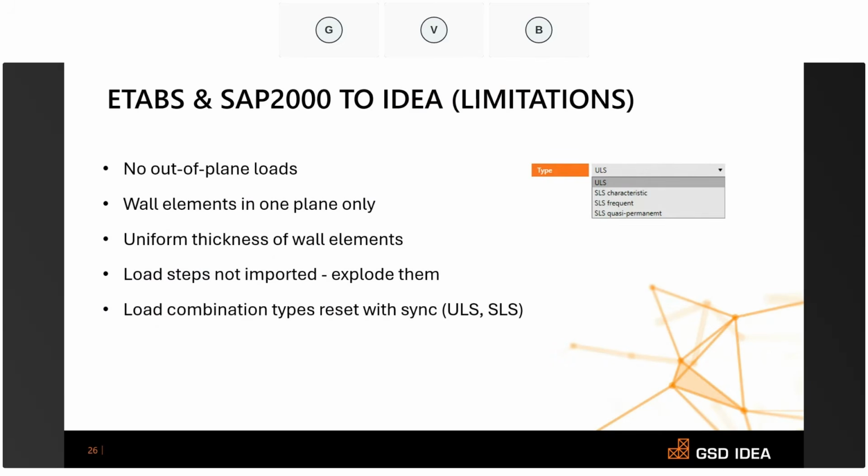Now, for concrete, when importing, if your ETABS model includes stepped load cases, IDEA StatiCa won't read all of them. So it's best, when you start importing, to split those into separate load cases before you start the import.